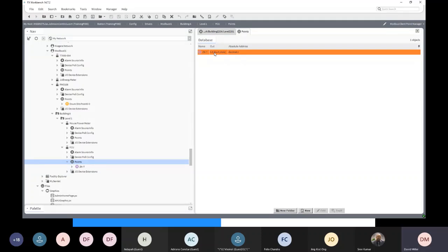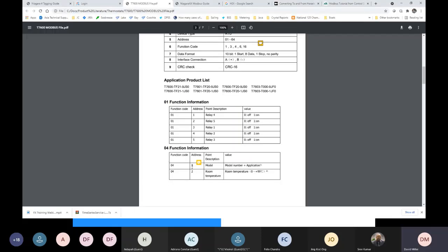All right, as soon as you've got that table, you have to read it and understand it. You got the document from the supplier, from the manufacturer. You have to read it and understand it, and it might be crystal clear. They might make it really obvious that when they say 0, they mean 0, and when they say 1, they mean 1. Or it might look like this table, where it starts at address 1. And that's a red flag that says, well, is that really address 1 or is that address 0?